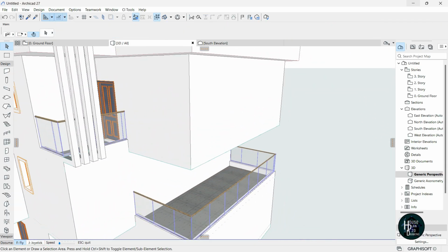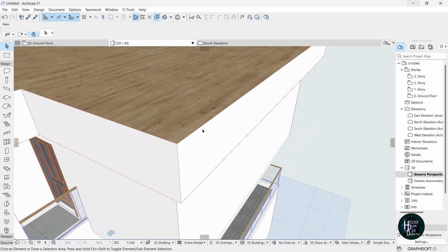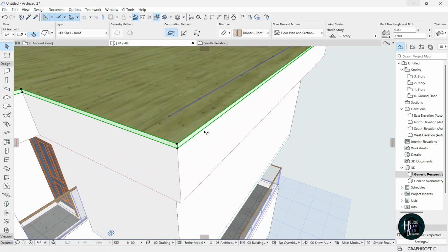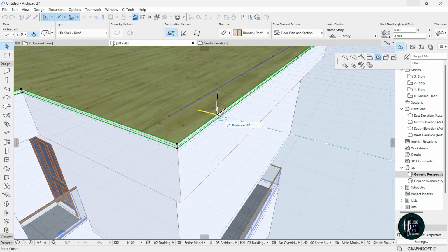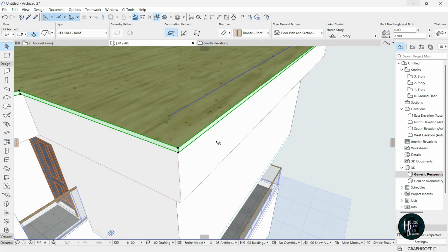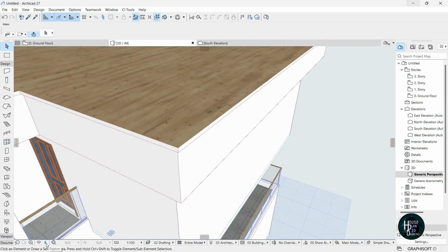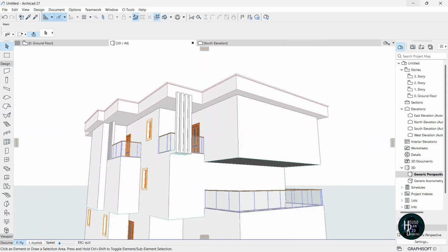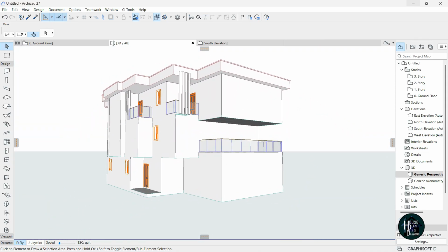Now moving closer. Okay, click this again. You're going to be clicking on this roof that I just created. That's this one, not this one. Click on this edge, make sure you're selecting this offset all edges, and give another distance of 50. Click enter. Okay, press escape on your keyboard and move down, and you're going to have the design come outside like so.